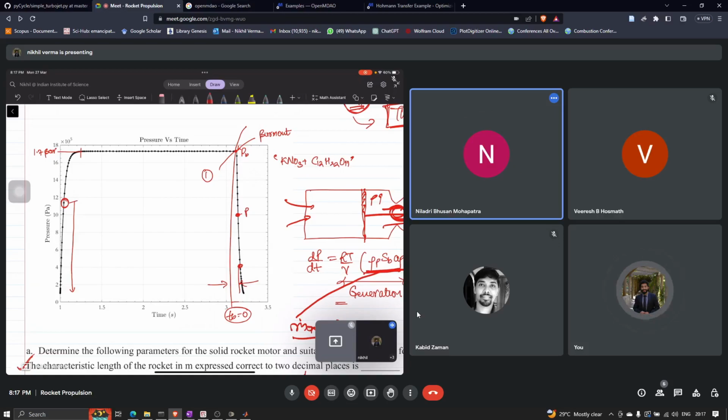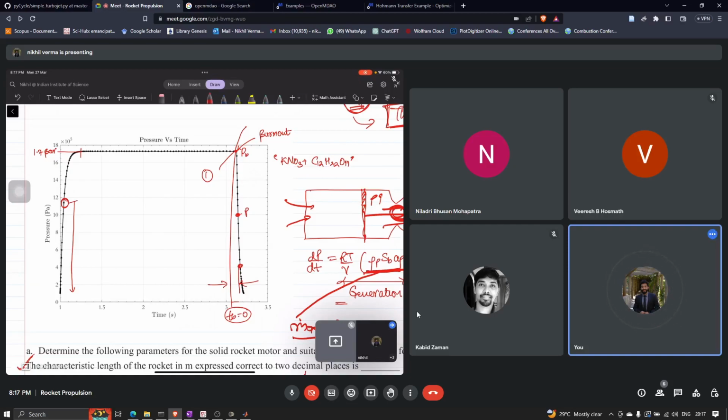First of all, let us not do that. What you should do is allow the mass flow rate going through the engine at a constant mass flow rate, such that you start building up the pressure. Once the pressure is built, you can vary your mass flow rate so that you can get your desired thrust values.